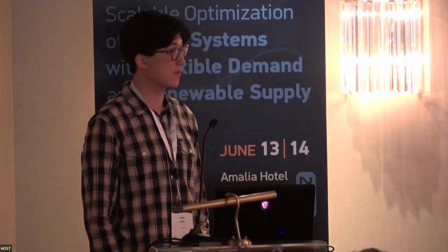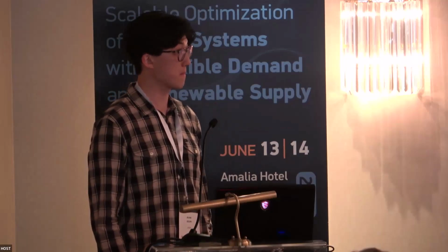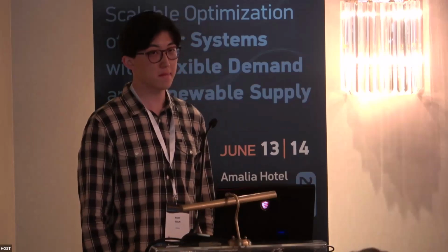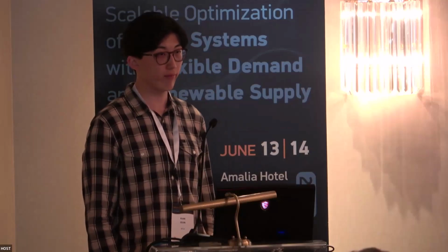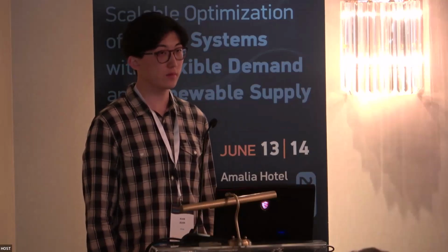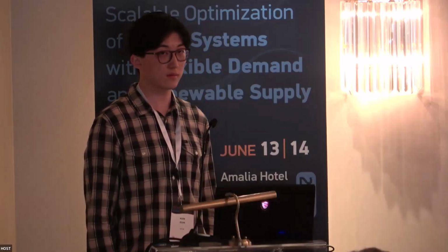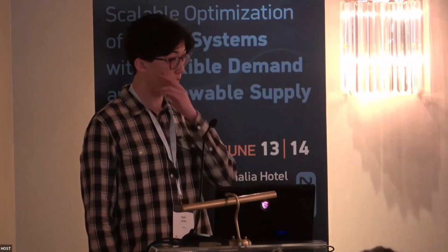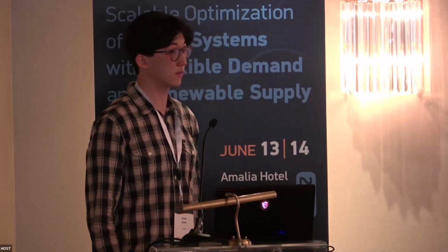There we get away with a single set of power flow constraints, whereas Karamanis would need an exponential number of power flow constraints because he needs to look at the combination of all possible patterns of activation. TSO1 doesn't activate anything, and neither does TSO2. TSO1 doesn't activate anything, and TSO2 activates fully. The opposite, and then they both activate fully. And in a mesh network, it's important to be able to get away with one set of power flow constraints as opposed to 2 to the n.